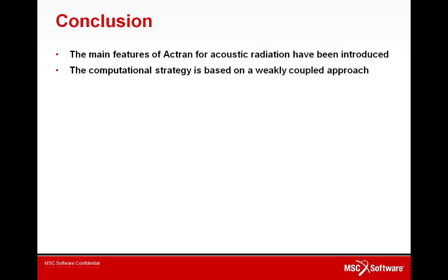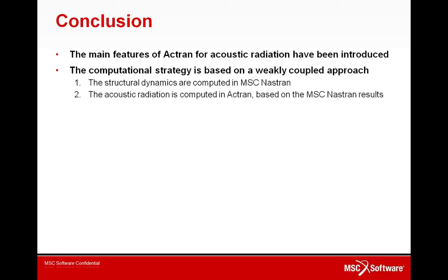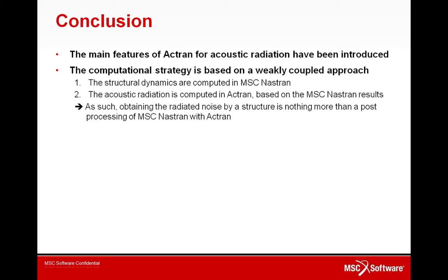So we have reviewed the computational strategy that is based on a weakly coupled approach, and it's a two-step procedure. The first step is the computation of the structural dynamics using MSC Nastran, and then the second step is the computation of the acoustic radiation done in Actran based on MSC Nastran results computed in the first step. If you think of the process that way, you can really consider that obtaining the radiated noise by a structure is nothing more than a post-processing of MSC Nastran results using Actran.